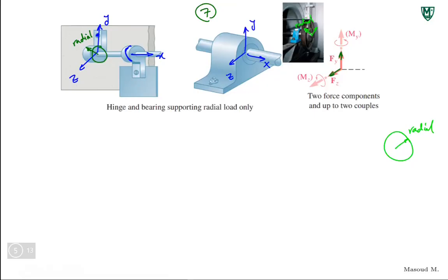Right? And the radial direction would be in this direction. I can do better than that. Radial direction would be in this direction. Any direction along the radius of the circle. We can prevent that. And if you look at it, the only kind of rotation you have, which is the main purpose of a bearing, is the rotation along the x-axis. Right? It rotates around the x-axis, but it cannot rotate around the z-axis. It's not supposed to, at least, and it cannot rotate around the y-axis.